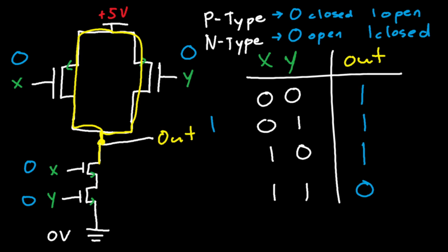So this is why this is important, right? You don't use resistors, you usually use transistors in real life. You use transistors because they're smaller, and they can actually prevent this current from hitting ground by just setting these transistors as the opposite of the transistors up above. So what I mean by opposite is just P-type to N-type. Opposites, right? And if I were to look at another example of, let's say, logic 1, 1, right? I'll work this through with you guys in case you don't have a mind of your own.